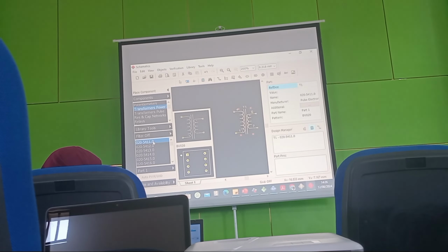If they tell you it is 12 volts, 1 amp, what you'll be getting here is 24 volts. Do you understand? But if you tie this and this together, you now get 12 volts, 1 amp.